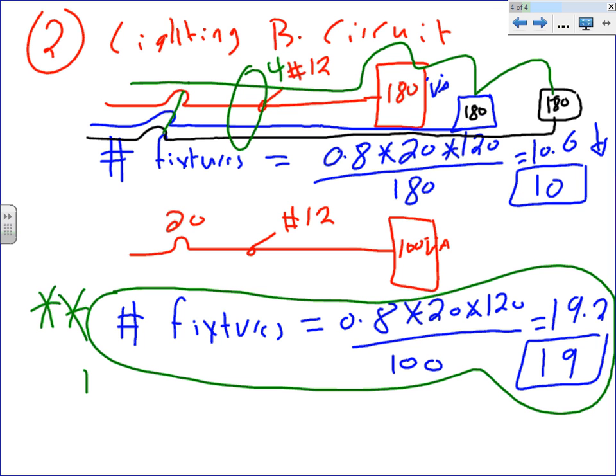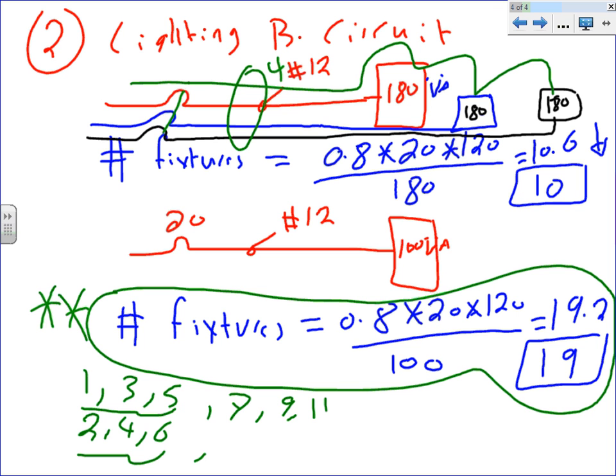So you're going to have a 1, a 3, and a 5, and a 2, 4, 6. Here's the first set of circuits that I'm going to fill. Then the second set, and then you go to the third set, which will be 7, 9, 11, and this will be 8, 10, 12. Does that make sense? When I fill these, I jump to these, and jump to these, and you keep going in 3-phase in a system.